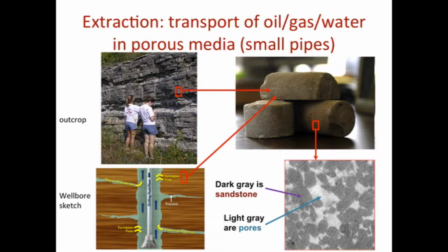Okay? So beware of two-dimensional modeling. In reality, you have to always double check your assumption. Your simplest model will always be two-dimensional. Ask yourself, well, what does this do to actual three dimensions? Because at 20% porosity, you will by and large never percolate from one side to the other. Okay. To percolate in two dimensions, you need about 55% or so.